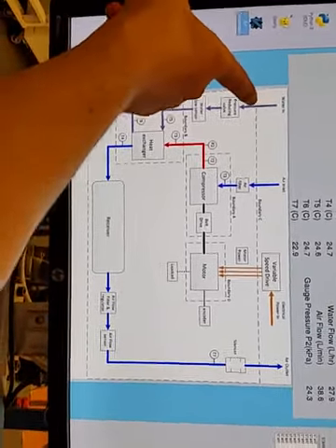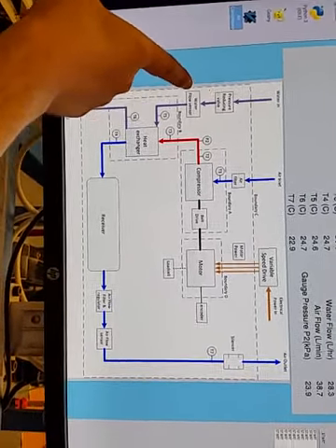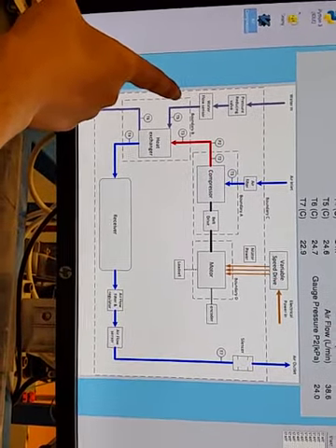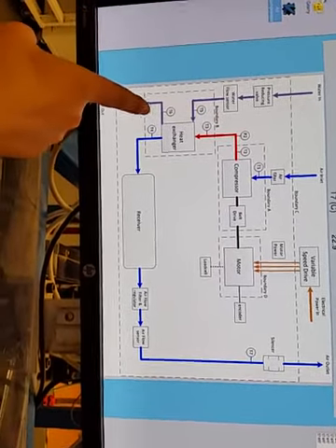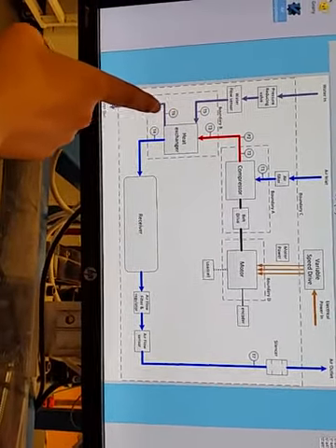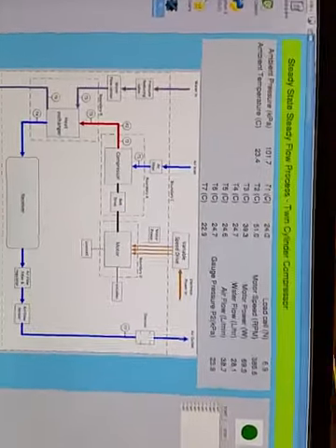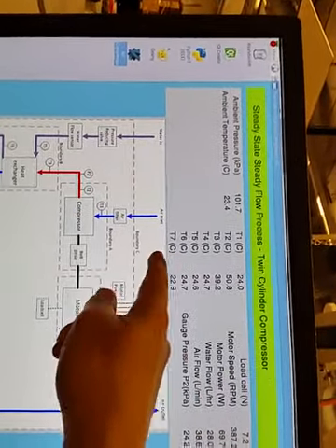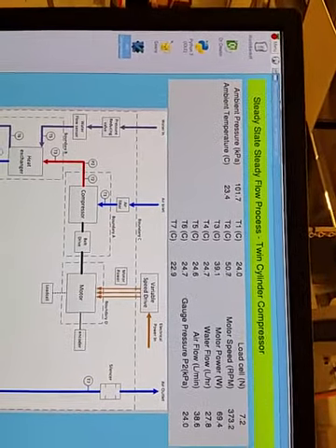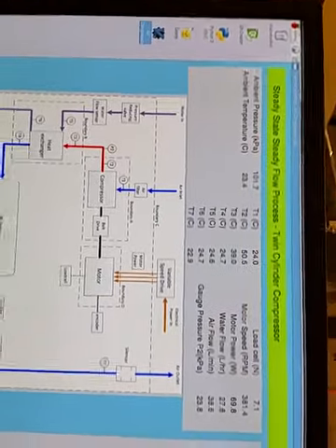Also, it shows us the path of water. The water goes in through a pressure reducing valve, then through a water flow sensor into the heat exchanger at a temperature T5, and it goes out at a temperature T6, and then to the outside. If you were here in the lab, the objective is to record these data, which are T1 up to T7, as well as the load sensor, the motor speed, the motor power, water flow rate, airflow, and the gauge pressure.